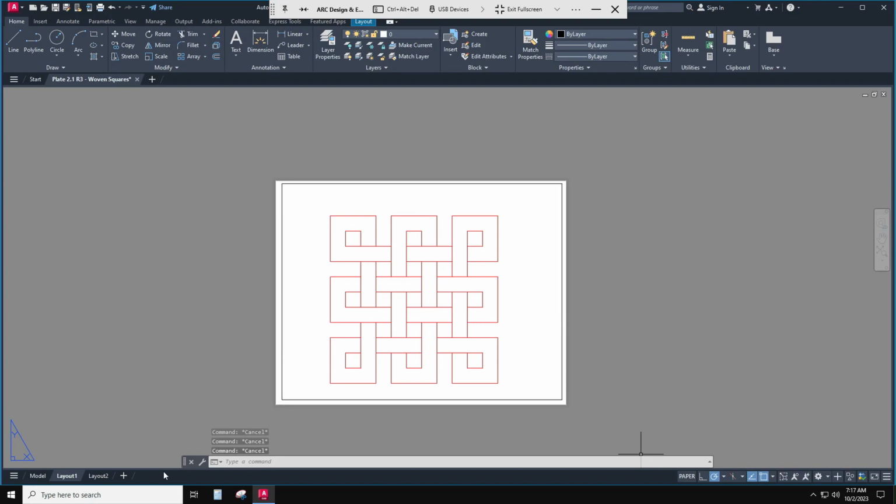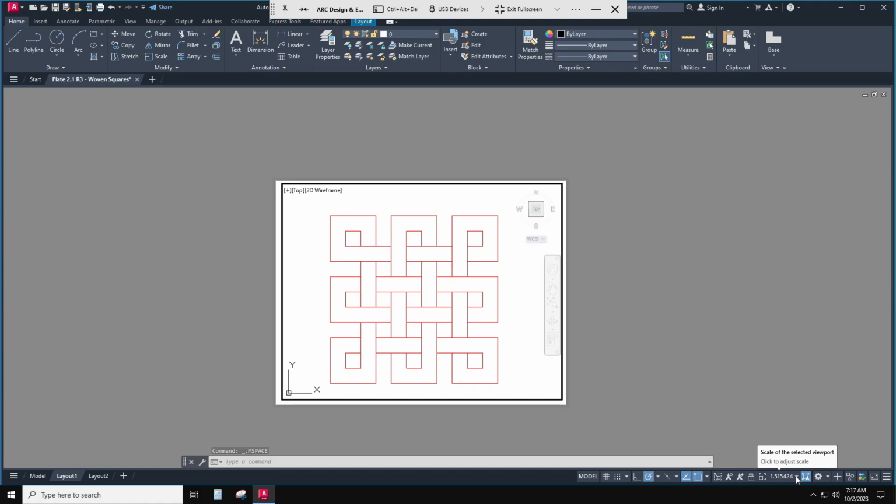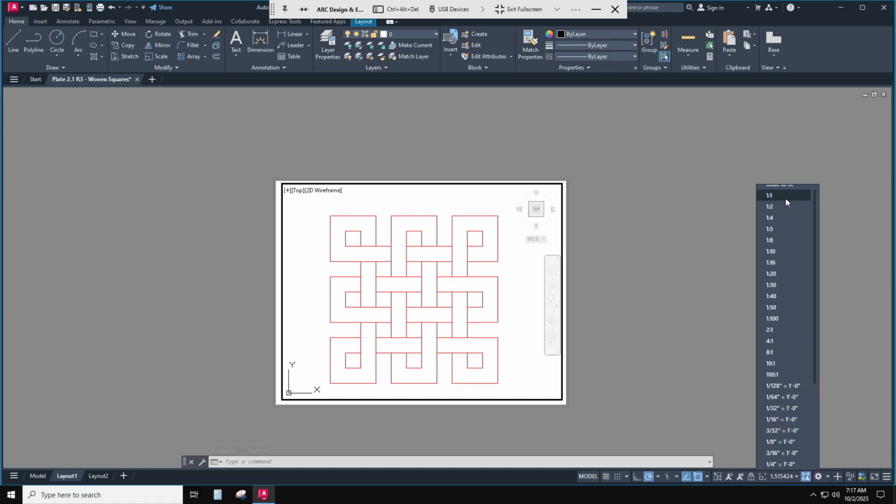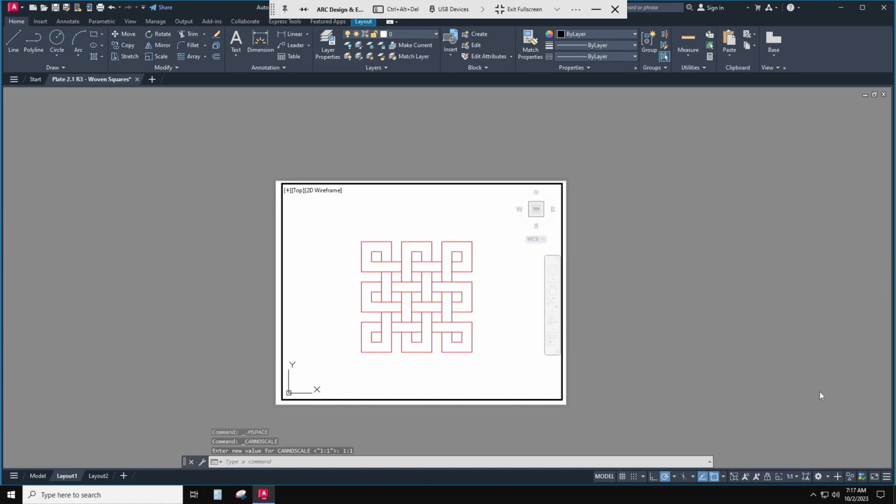Remember, I'm in my viewport, I'm on my layout, and I go paper changes to model, and I have to change my scale to 1=1. I think that's a good looking scale. Any of the common ones in there, lock it, and come back to model. So that was all of what we used to call R1.